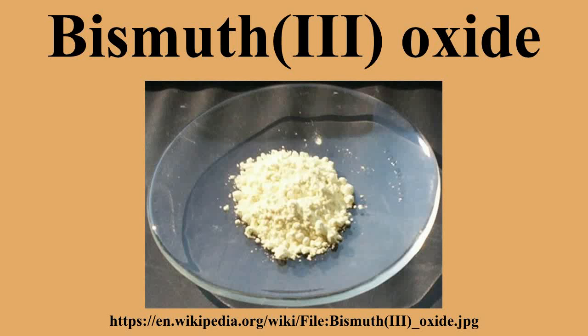Furthermore, their ionic radii decrease fairly uniformly from La3+ through Nd3+, Gd3+, Dy3+, and Er3+ to Lu3+, making them useful to study the effect of dopant size on the stability of the Bismuth Trioxide phases. Bismuth Trioxide has also been used as sintering additive in the scandium oxide-doped zirconia system for intermediate temperature SOFC preparation.